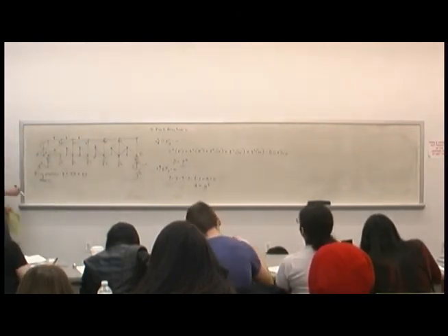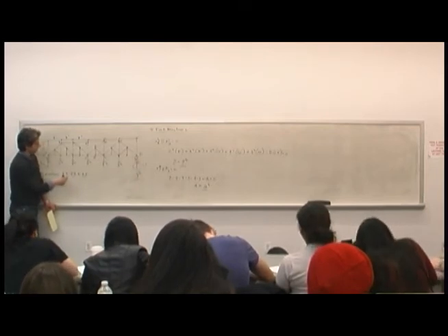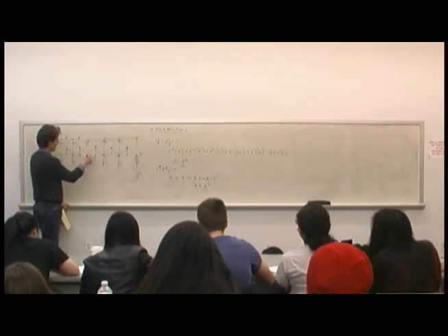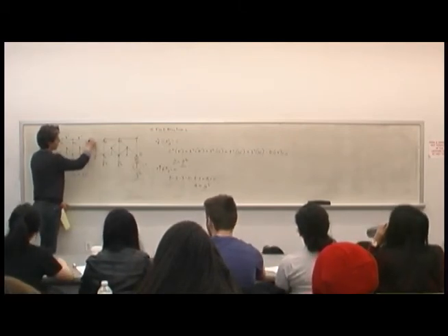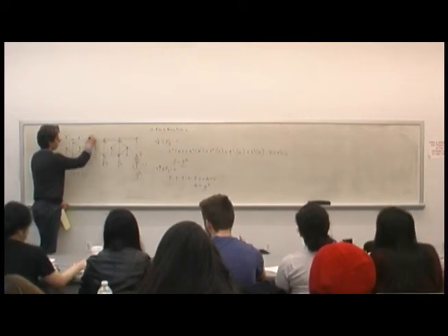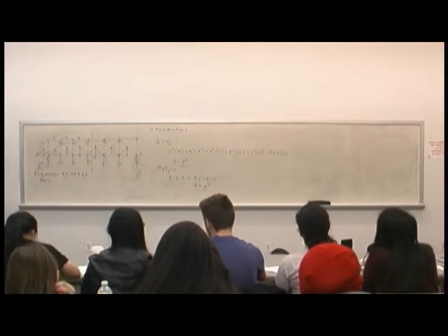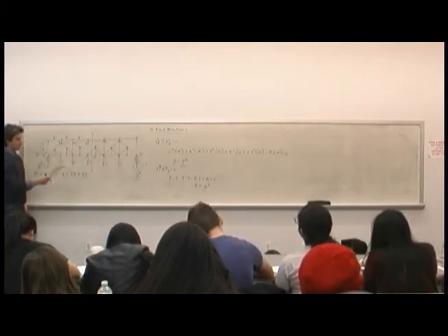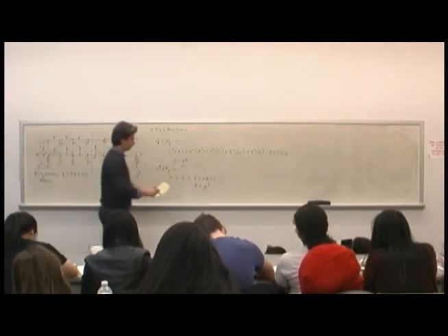So the problem at hand then is to find the forces in these members. It's this one, it's JK, and it's JH. So I'm going to do a section cut right through here. With that, I'm going to do a free body diagram of one side of this truss or the other. So let's do our free body diagram.